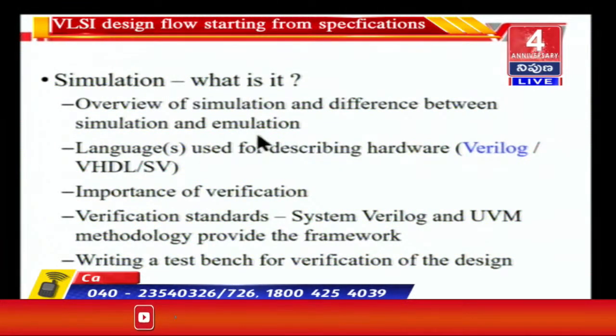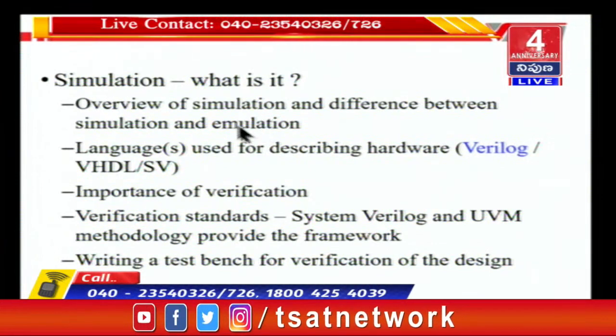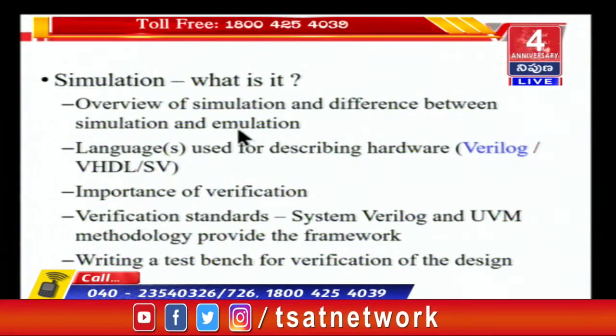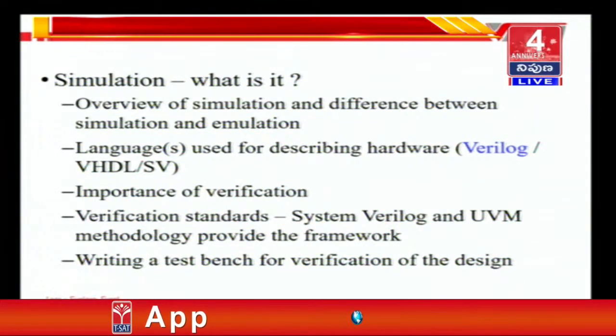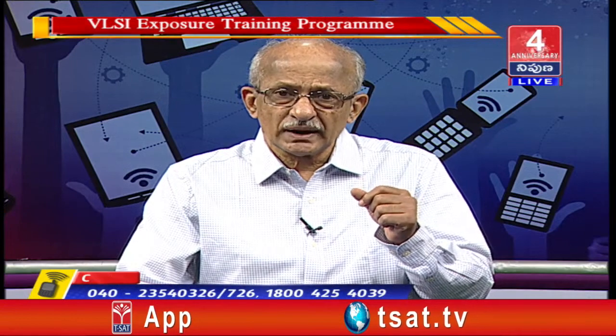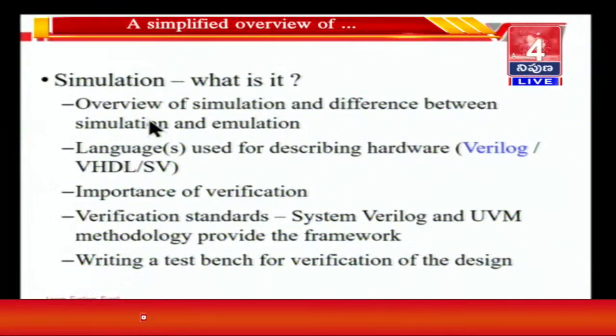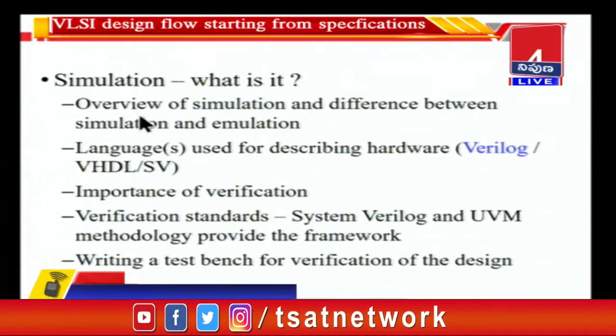This is a completely hardware thing. You don't write a program in assembly language for an FPGA. An FPGA executes the design directly, whereas a microprocessor or a microcontroller executes your function through a series of assembly language routines or through a series of instructions.